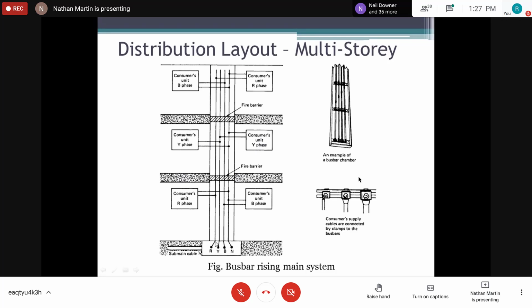And this is basically in a situation like a building where we have different floors that deal with different aspects. Each floor should also have its means of isolation, right? So they'll have their consumer unit or their panel box that disconnects that particular floor. Very critical when we're talking about a multi-story building.